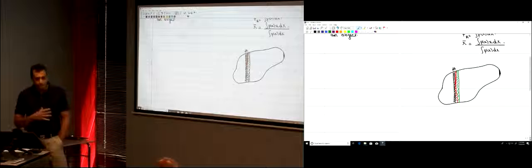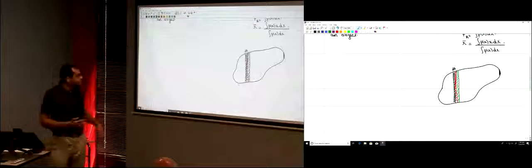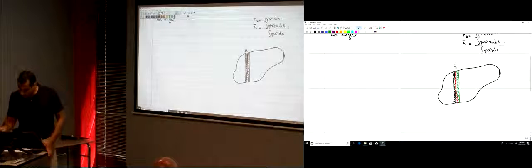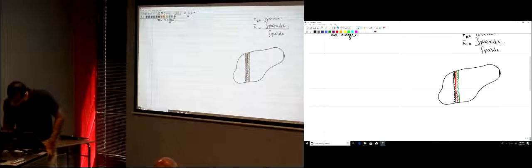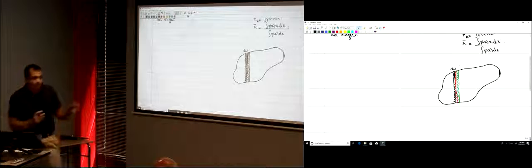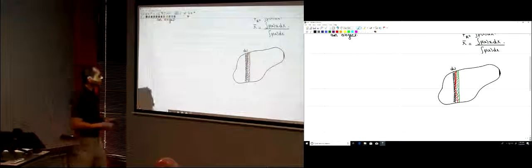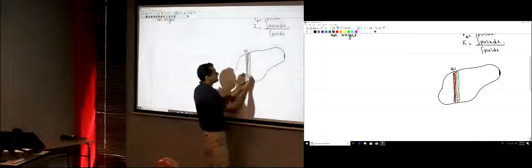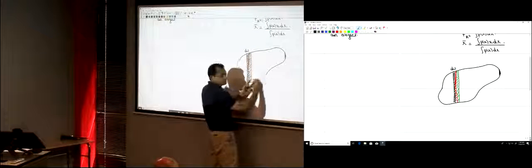And from that we can find the weight of the entire body. So instead of writing dA here, I'm just going to write dW, the weight of each of those segments. Okay? So the weight of each segment is not the same. It depends on its area, right?